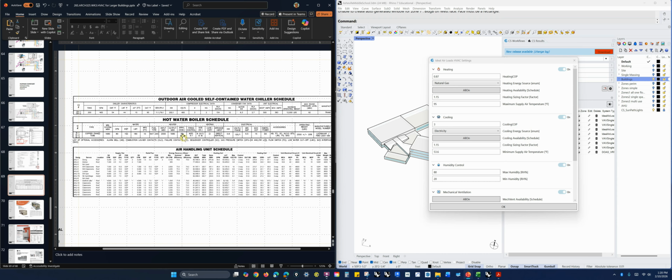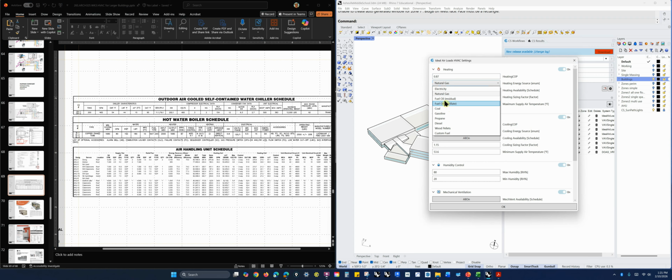So what we're doing here is setting a conceptual mechanical system that doesn't have any ducting or delivery system. We're just saying we're designing a system, and the simulation is going to run as if it's just sort of magically putting the temperature that's needed into the zone. Its efficiency is going to be determined by the settings we have here. The reason this is natural gas, we could pick a different one, and that would have a different primary energy and a different carbon footprint. But we're not going to worry about the complexity of modeling ducting, and that's just an energy modeling trick here.